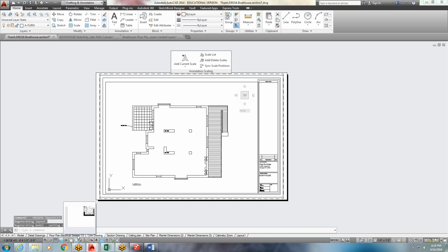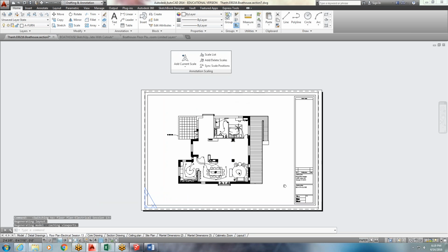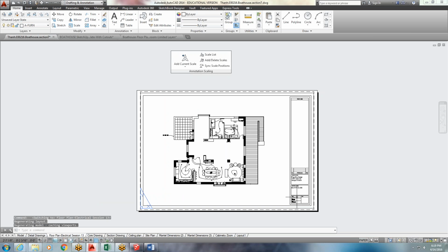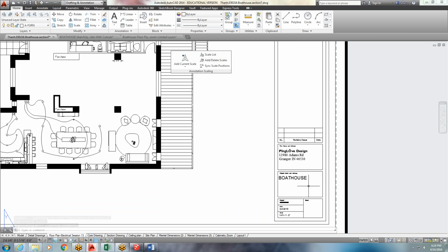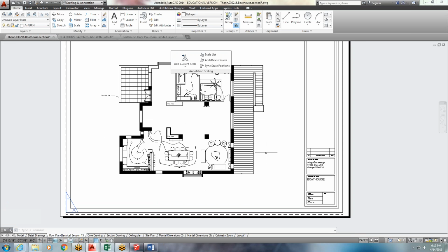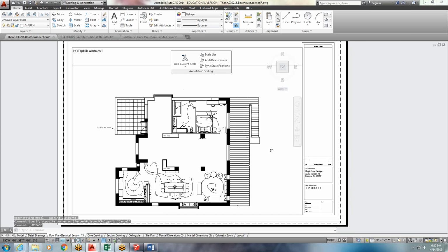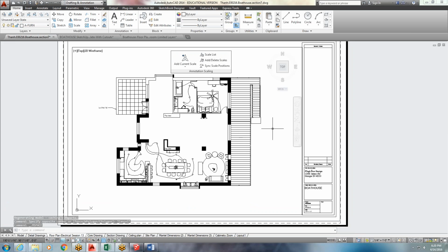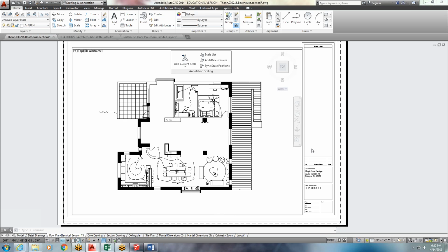Floor plan electrical session 13, where you have your new drawing on your own title block as you had already updated it last time you turned plans in PDF through AutoCAD. You want to make sure not only is it centered, but it did accurately stay 1/4. It should have if you just panned, where I just dragged it up and down. So it kind of functions as SketchUp. As long as we pan and do not orbit, we're okay. It stays at the scale we want it to be.